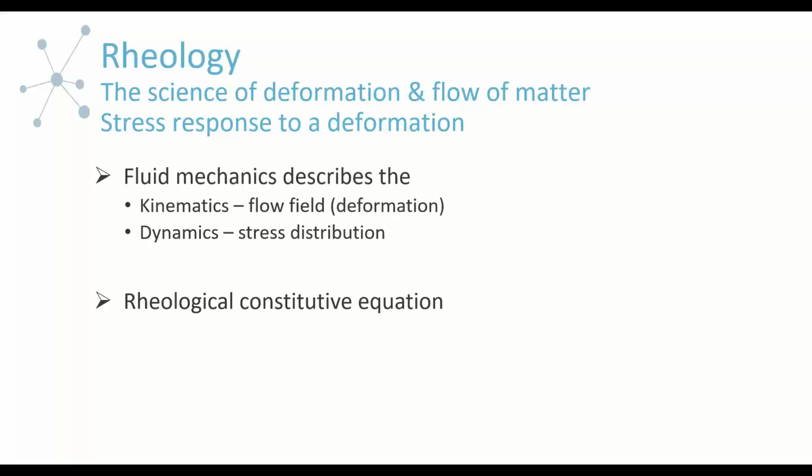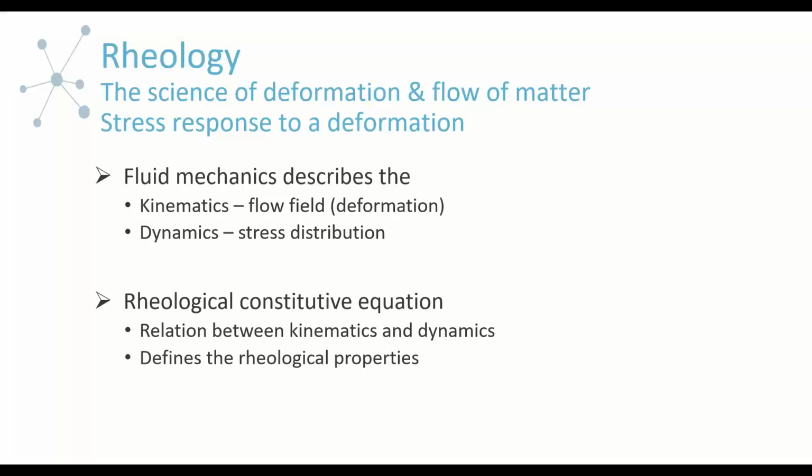So these two components lead us to what we refer to as the rheology constitutive equation. And constitutive is just the language we use for relating these two components. It's the relation between the kinematics, or the flow field, the deformation, and then the dynamics, or the stress. And this is what defines all the rheological properties. There are many rheological properties, and this is what distinguishes them. So it's going to be a proportionality between stress and the deformation.